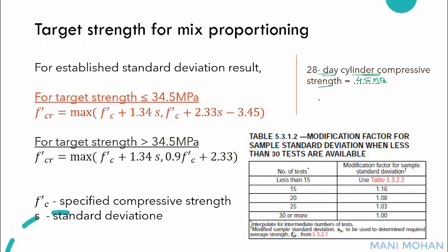For concrete proportions to be acceptable, the average compressive strength of concrete from trial batch test must be equal or exceed the target mean compressive strength. The standard deviation established from test records is a measure of the concrete supplier's ability to manage the variability of materials, production and testing of concrete. When a concrete production facility has a suitable record of 30 consecutive tests of similar materials and conditions expected, the sample standard deviation is calculated from these results.